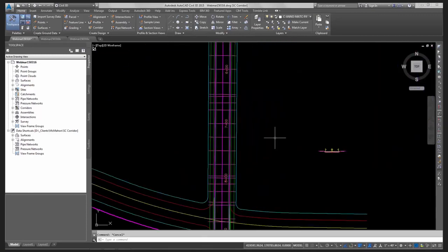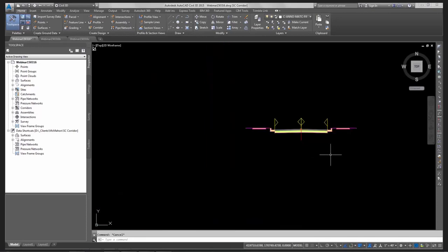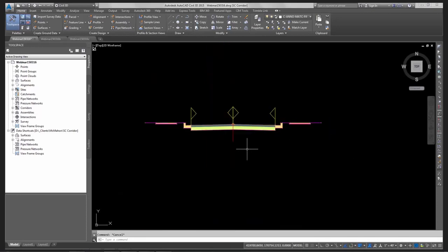And what I want to do is I want to build a conditional that will drop my curb and everything outside of the curb, it'll drop it in everything from the edge of travelway outside. It'll just drop it. So here's my basic subassembly.